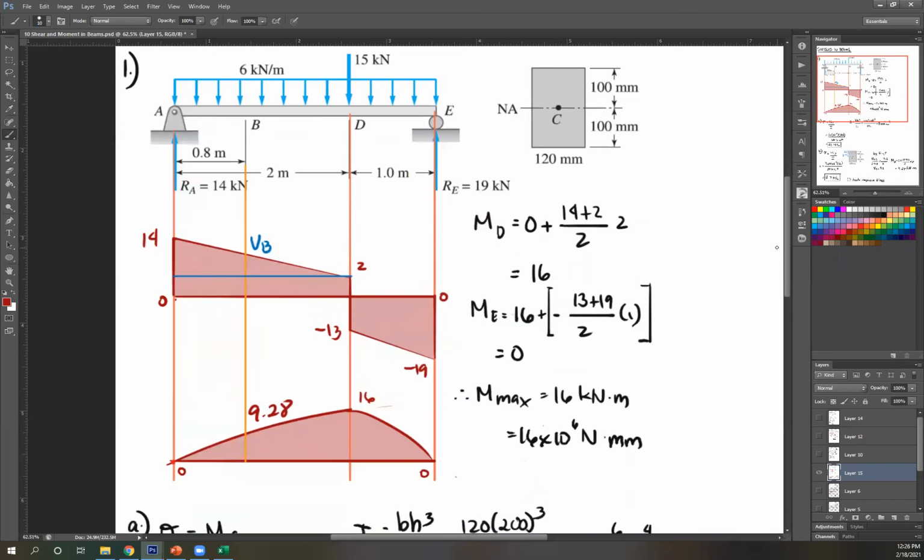Next, which is what we're concerned with, your moment diagram. Because from this, we'll get your maximum moment to know your maximum shear stress. So again, these are simple supports, therefore, moment there is 0. So 0. Next, look up here. This is an area above your reference line. Therefore, I have a positive slope. This is a sloping line. Therefore, one degree higher is a parabolic line. So I'm going to draw a positively sloping parabolic line.